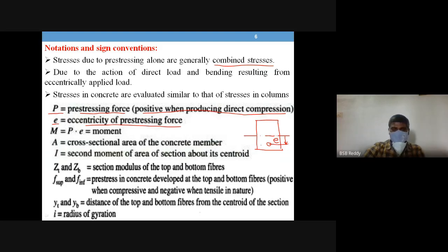If you have multiple levels of pre-stressing tendons, for example one more duct somewhere here, one more duct somewhere here, as you have seen in the example of preparing a post-tensioned box girder, where there are so many locations for ducts, in such a case you have to work out a common location, that means the CG of the tendons, instead of just a single location.